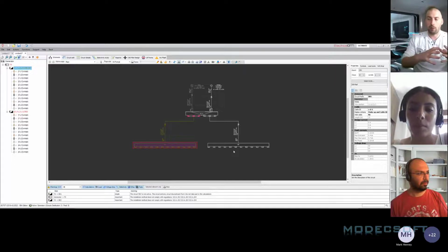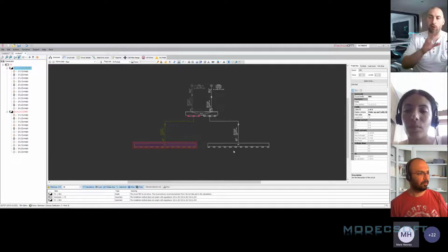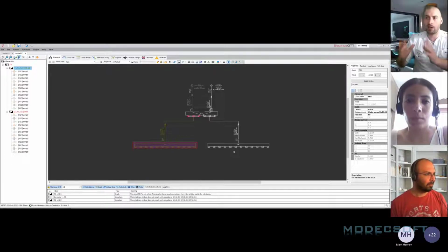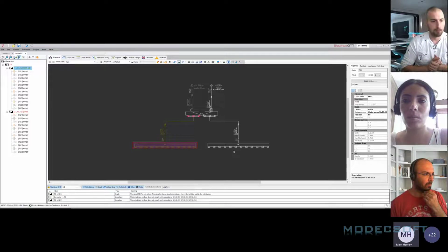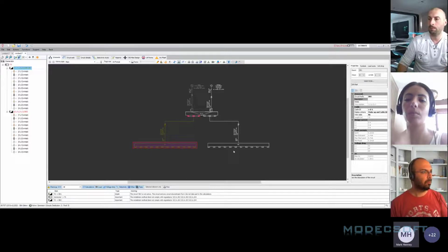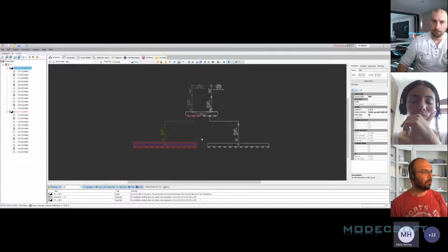So it will depend upon how you set the information up in the core software, and your design will affect how our final test data and information will appear in our reports. So into your warning sections now, if I had a 32 amp supply and circuit breakers, but the supply was big enough, that will all be good. But when I switch to generator, it may give me warnings to say you're not going to get disconnection times.